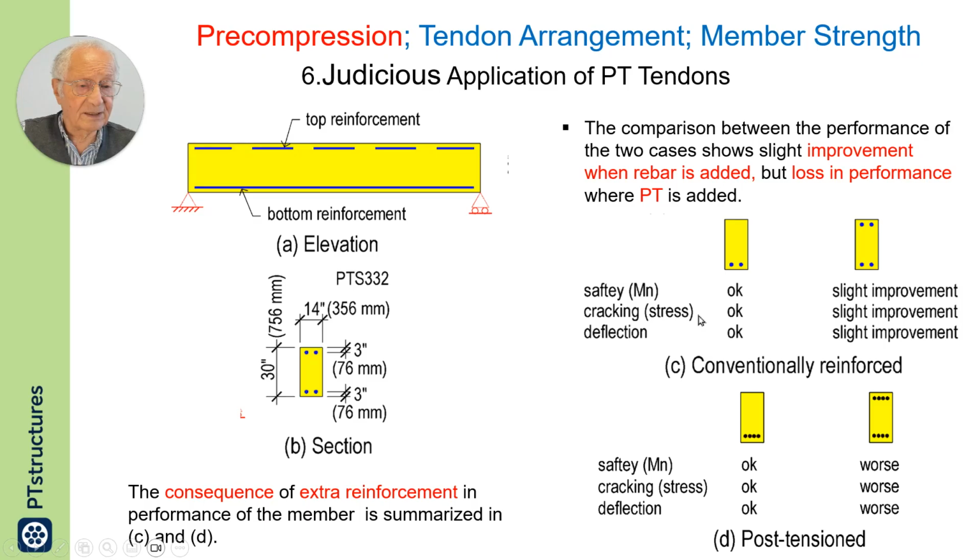For cracking, it slightly improves because it gives the member added stiffness. For deflection, slightly improves. Deflection will be improved because the member is stiffer.